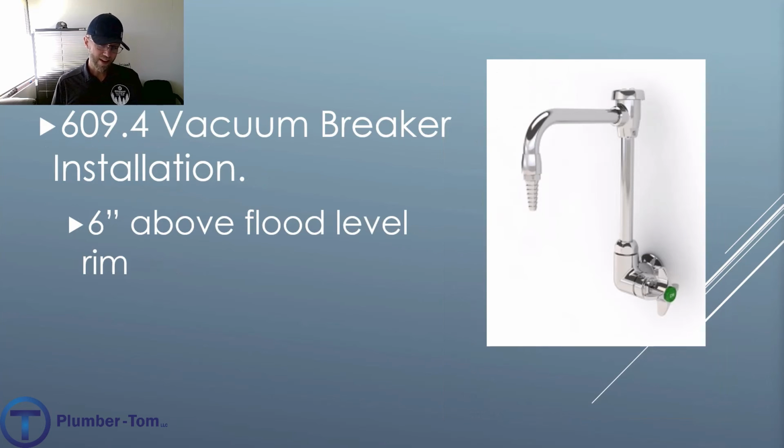609.4 talks about vacuum breaker installations within those healthcare facilities, and stating that those vacuum breakers will need to be 6 inches above the flood level rim. We'll see this in our presentation as we look at backflow preventers, but that's what this is all about, preventing backflow into any of these laboratory type fixtures.